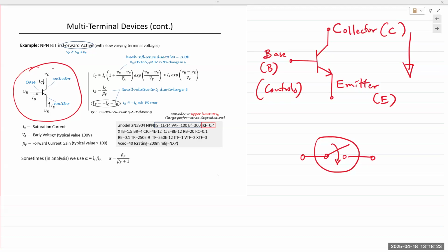Oh yeah. So we have current flow going from the collector to emitter, and then the base is the third terminal that actually controls the flow of current. It controls the flow of current, which is not possible in a diode, not directly at least. In a diode, you apply voltage, the diode turns on, forward bias, and current starts flowing. If we wish to change the flow of current, then we must change the supply voltage or the supply current. But we cannot apply another signal on top and control the flow of current directly. In a transistor, we can do so because we have a third terminal.